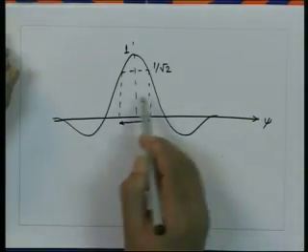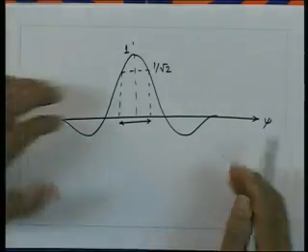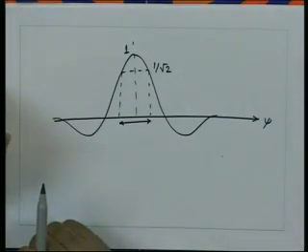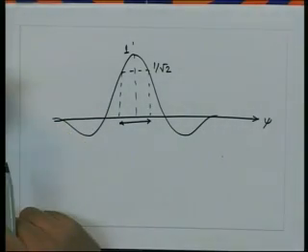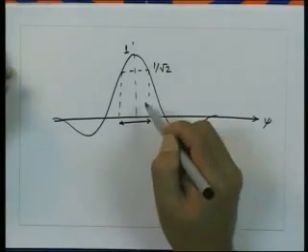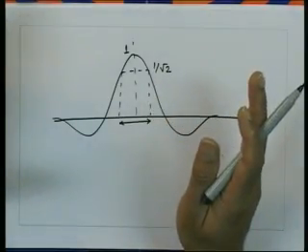So, I can get first the half power beam width in psi, and then from there I can convert that half power beam width into the physical angle which is phi. However, in this case again we have to take the radiation pattern, equate it to 1 over root 2, solve the expression and then find out the directions. From there we can calculate the half power beam width.